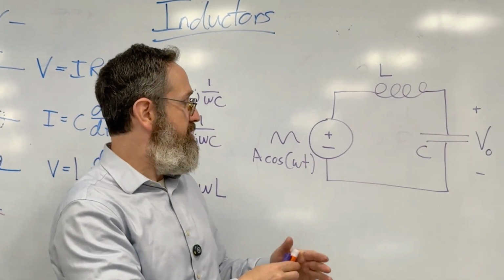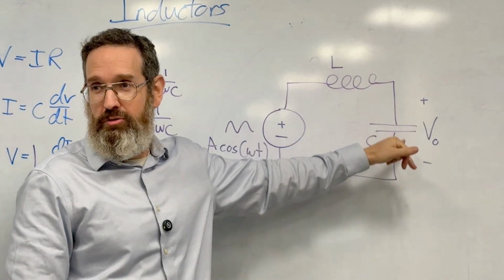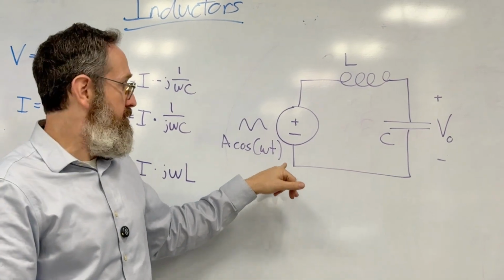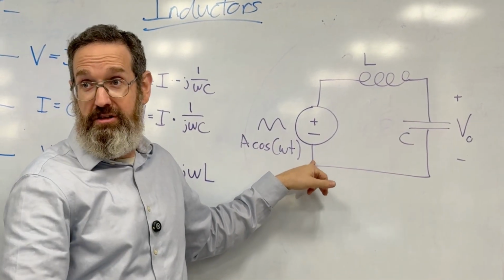To write out the equations, if you remember, the voltages always have to add up to 0 as you go around the loops. You start with a certain voltage and you add, it always has to come back to where you started. It's like height. You go up and down, but you have to come back to where you started.